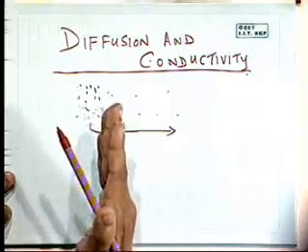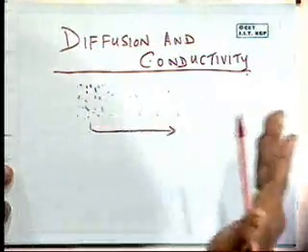So in addition to my drift current, which is in response to an applied field, even if there's no field, if I have a concentration gradient in the material, then I will expect the flow, say for electrons, from one end to the other, which constitutes a current. So even in the absence of an electric field, there will be current flow, right? So there's both of these aspects that are there.